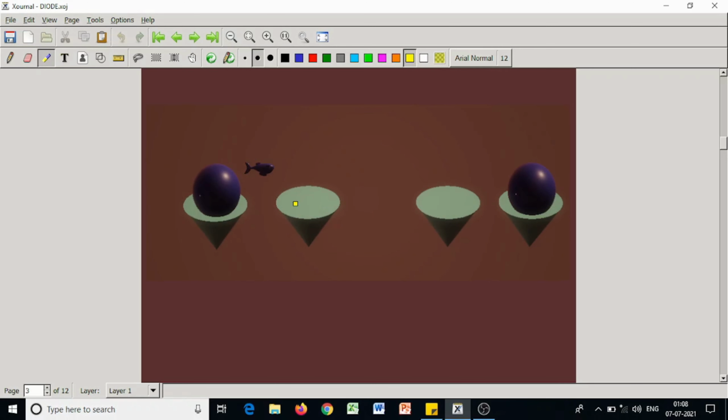and as it is a lack of negative charge, it is considered a positive hole. So as the electron swims towards the right, the hole swims towards the left. So the motion of the electron is opposite to the motion of the holes. But in any convention, the direction of current is opposite to the direction of flow of electrons. So electron current is also in the left direction and current due to holes is also in the left direction in this figure.